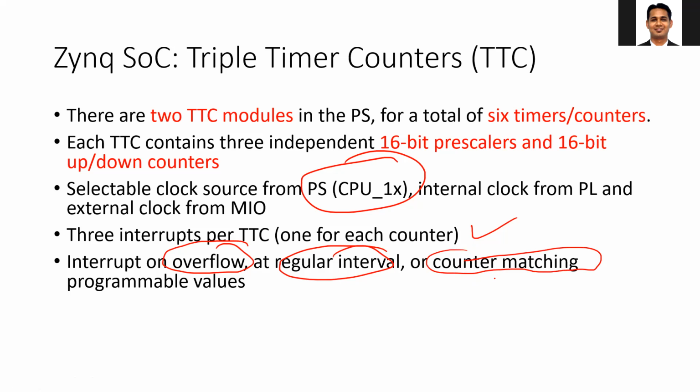So you have additional registers. For example, your counter is counting from 0 to X. In the private counter, whenever it reaches 0, it generates the interrupt. But in the case of this TTC, suppose you have a value Y, it will generate the interrupt whenever it reaches 0, and also another interrupt when it reaches Y. These are called match registers, and there are 3 match registers available.